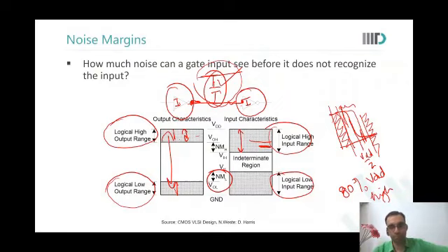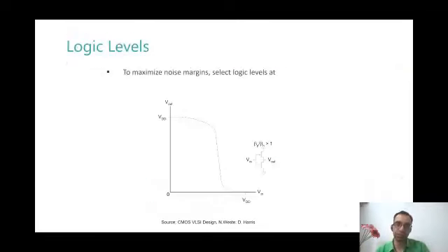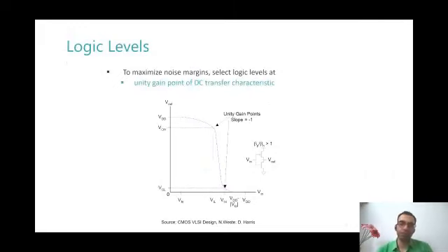Thank you. Okay. So I know these many questions because we want to increase the noise margin. So how do we increase the noise margin? Sir, we can make beta P equal to beta N so that our curve goes steep at a point so that we would have a good noise margin on the top and the bottom. Yeah. So if beta P is equal to beta N, that is how we can do it. Before that, we need to see what is really the noise margin.